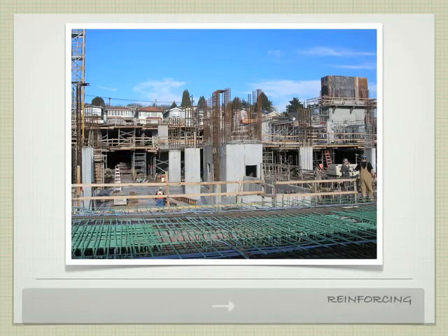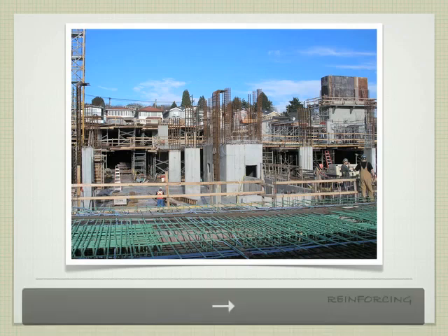Okay, so looking at it a little bit here on a construction site. In this particular example, it's hard to see through this a little bit. By the way, what's the green tell us? It's epoxy coated, so it's in somewhat of a toxic environment. So we want to be aware of toxic, not toxic chemicals, toxic salts, that kind of stuff. Okay, but if we look really carefully underneath this mesh of reinforcing, we can see the bottom surface of the slab, and we can also see the beam or the girder being formed out that would go down in this depression, and it comes back up and is there. I think I have a couple more examples here in a second.